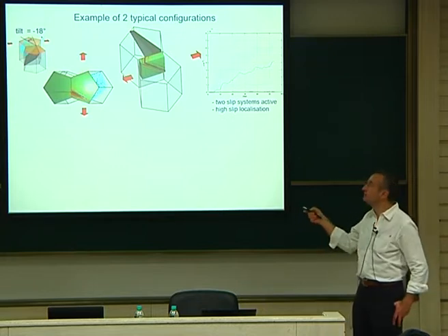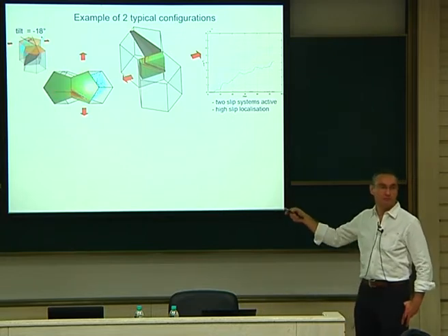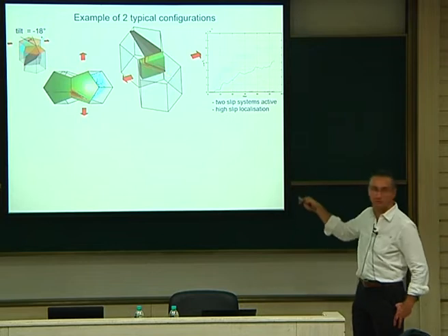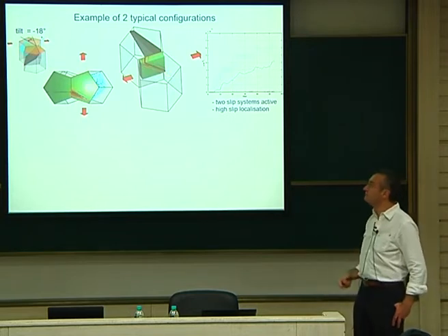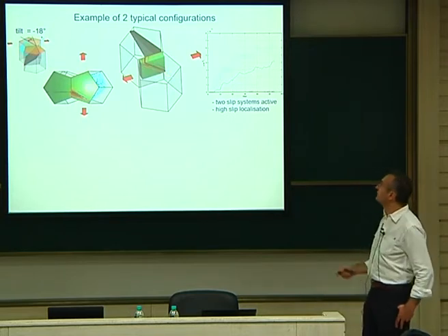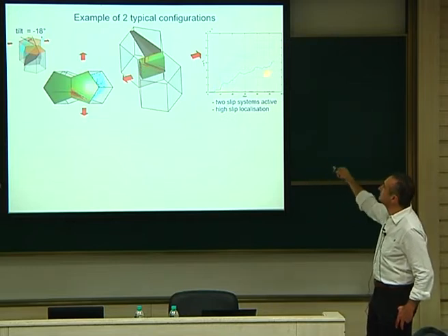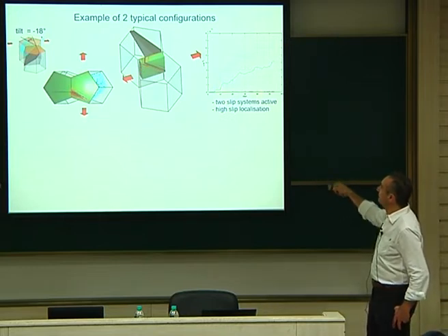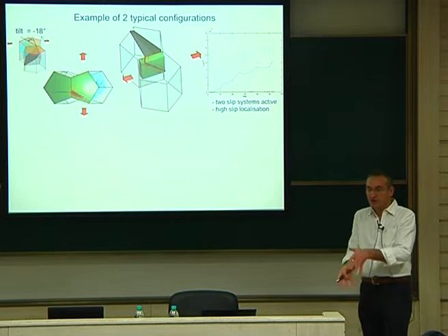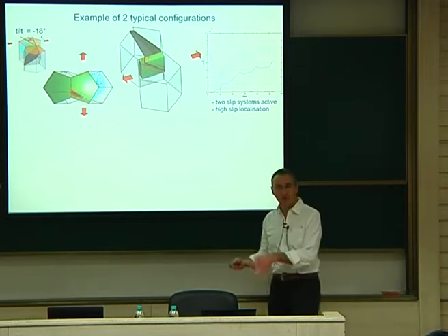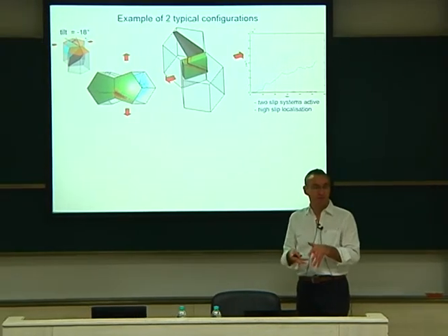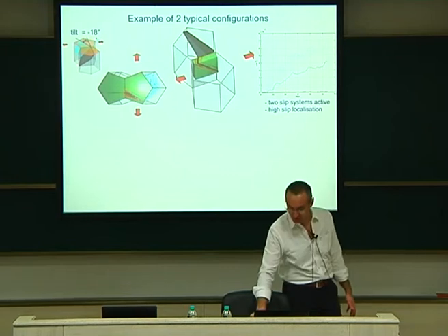In that orientation, the crack will be easy to move and to nucleate again here and to create a new crack. So you will have a very fast process for cracking. And you can see in that region that the dislocation density evolves quite fast, and the others are not moving fast, so it means that it is really localization of plasticity. So I would say that this is nefarious for the material. It's a very fast damage process.